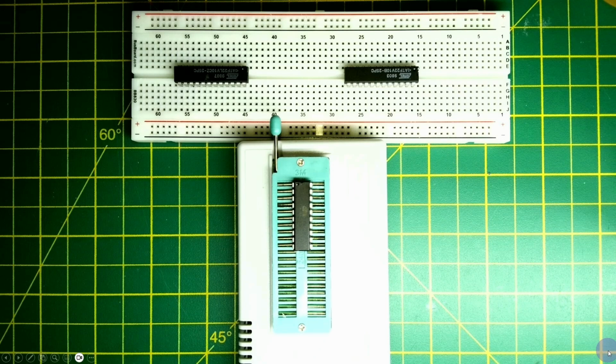Welcome to Breadboarding. In the previous two videos we've covered an introduction to programmable logic devices and have also gone through all the documentation available on the CUPL programming language, which is used to program these chips. The first video we covered the ATF22V10, which is probably the easiest to use chip and is the one I've used most in the Breadboard PC project.